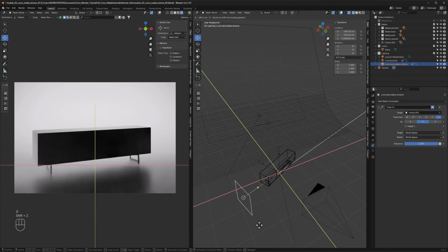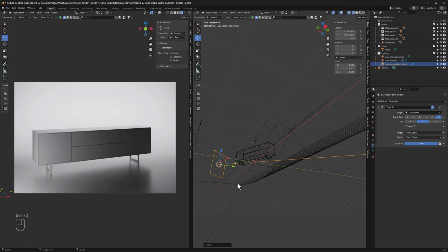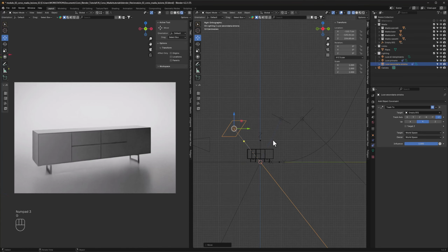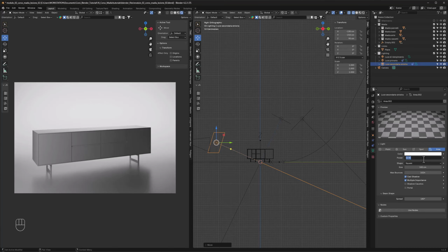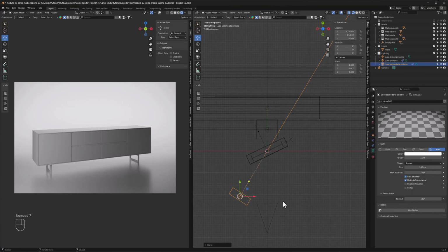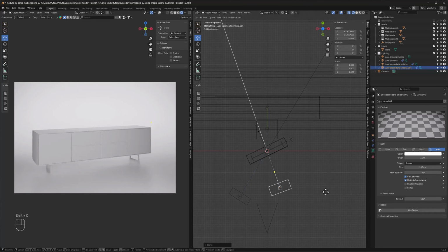Place the light according to these guidelines obtained from the various tests carried out previously. Set the X field to -130 cm, the Y field to -210 cm, and the Z field to 90 cm. Let's also open the Lights panel and increase its power, setting the value to 15. Now, using the Shift-D command, let's make a copy of the light, and immediately confirm with the Enter key.